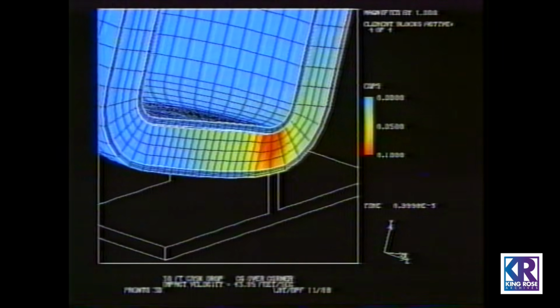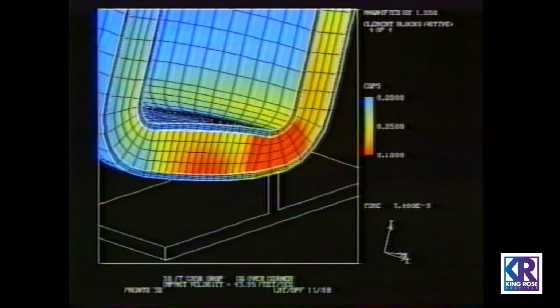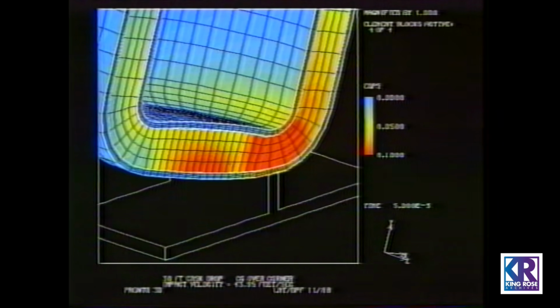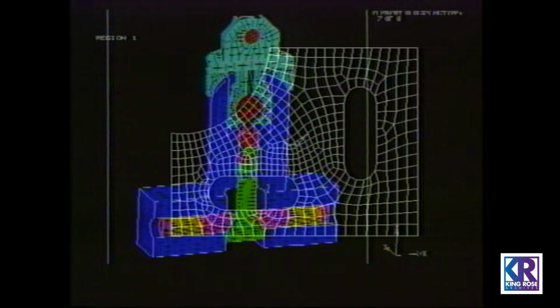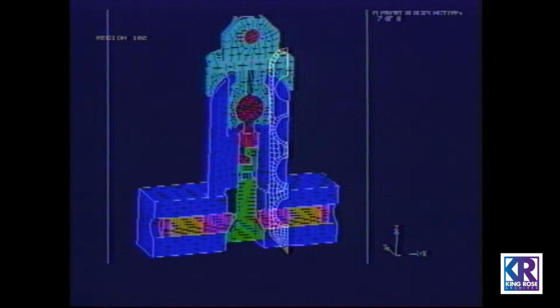Sandia researchers are developing a technique called paving to automatically generate well-formed finite element meshes in arbitrary geometries. Solving very large problems enabled by the new capabilities of massively parallel supercomputers requires generating large finite element meshes. Paving significantly reduces the time required to produce a high-quality, large mesh. Paving is particularly adept at transitions between various sized elements while maintaining reasonable individual element shapes.